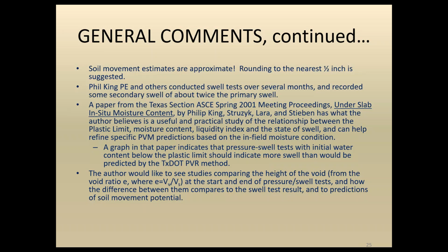They present what I think is a very useful and practical study of the relationship between the plastic limit, the moisture content, the liquidity index, and the state of swell, and just some reference to that paper can help refine some specific potential vertical movement predictions if one wanted to consider the in-field moisture conditions at the time of the sampling.